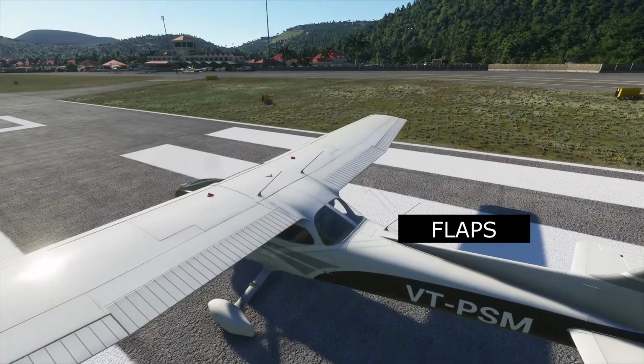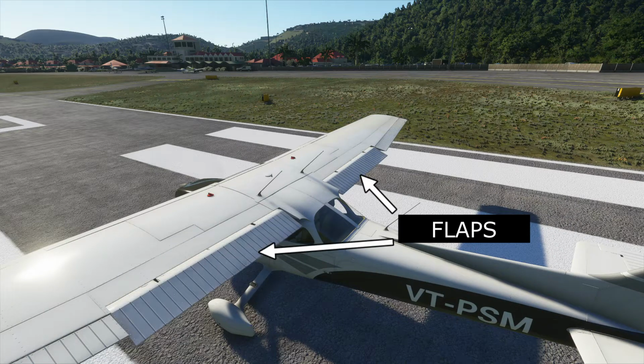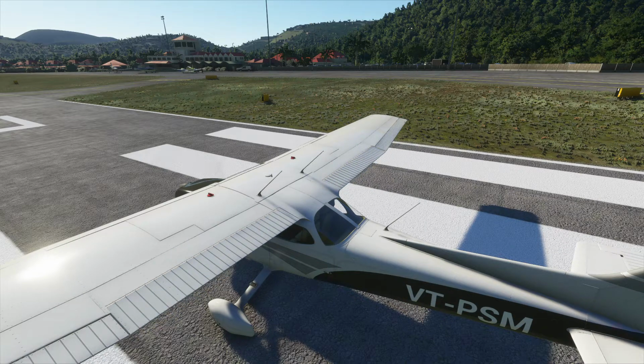Flaps extend outward from the fuselage to near the midpoint of each wing. The flaps are normally flush with the wing surface during cruise flight. When extended, the flaps move simultaneously downward to increase the lifting force of the wing for takeoff and landings.